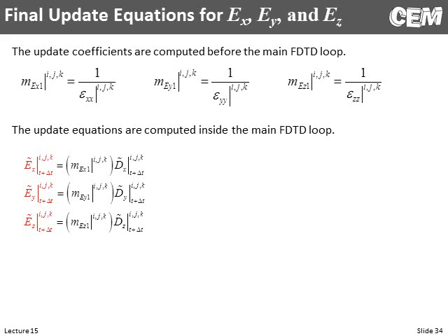And if you just have constant dielectrics that are isotropic, it may not even make a whole lot of sense to pull out that constitutive relation, but it makes a whole lot of sense when you're not sure what to do with that. You might want to modify your code to do anisotropic materials. You might want to modify it to do nonlinear or something else crazy. So I like to pull it out. Sometimes I'll even pull out the B equals mu H if something crazy is happening with the permeability.